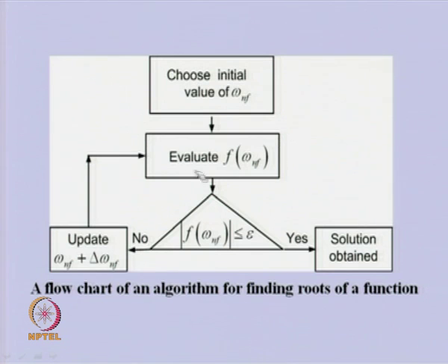So this cycle will repeat till we get the desired accuracy of the natural frequency, and that will be the solution. And once we get one solution, we can search for more depending upon the degree of freedom of the system. So we have seen what the procedure would be to solve the frequency equation for a larger system. In this particular case, obviously numerical computation will be required to obtain all the roots of the natural frequency.